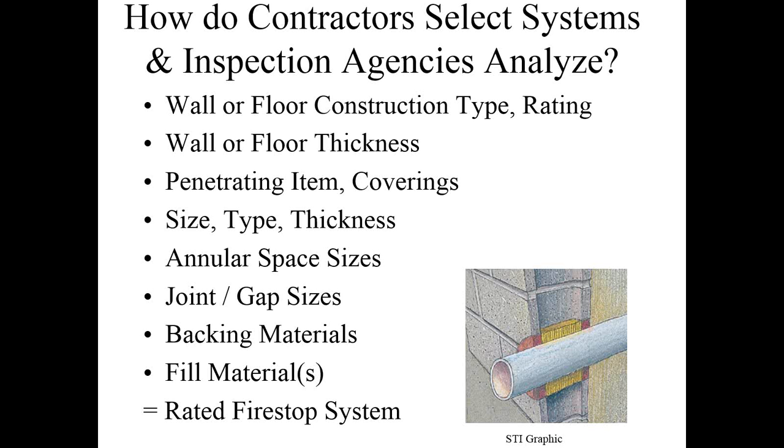There's also a second reason. The structural capability of that floor is set up through ASTM E119 or UL 263. Those are the test standards for the floor or the wall itself. The test standard does not test the wall or floor with any holes in it. So in order to represent the ASTM E119 assembly, the assembly has to be solid or protected or continuous. So that would mean fire stop.